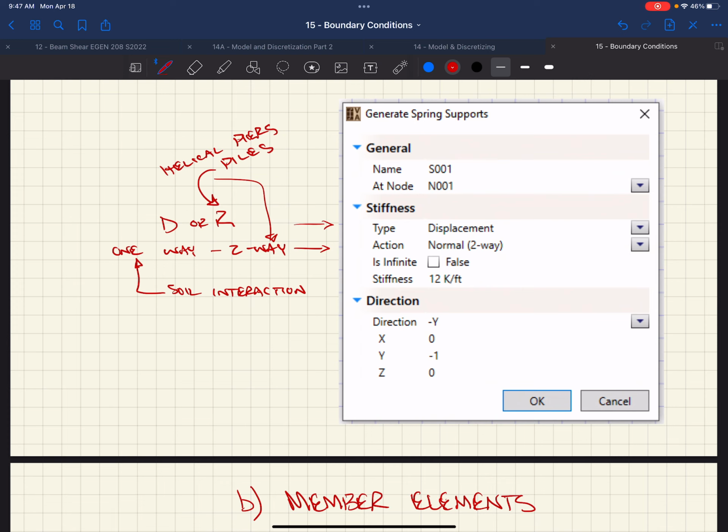I mean, if they're putting in 500 of these underneath this house, right? Those helical piers have a lot of strength associated with them, right? And if you put them in a few strategic locations that were battered, you'd probably get the lateral load out of that. Because they literally just start screwing and then they lay it over and then they screw it into the ground. Is batter just being at an angle? Yes. Yep, battered would be it.